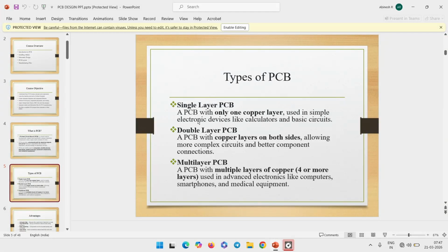Okay, in order to reduce the presence of a large number of components in the same layer, we split the components and place them on the top and bottom layers. So they have enough space on the PCB. At the same time, the top and bottom signals need connectivity. In order to connect the top layer and bottom layer, we place vias.